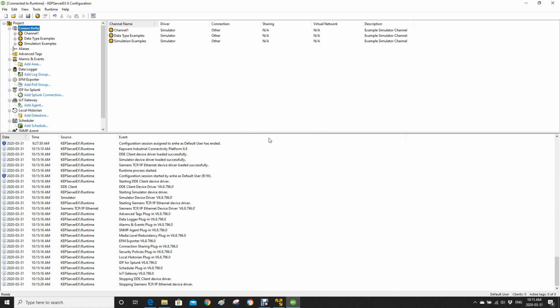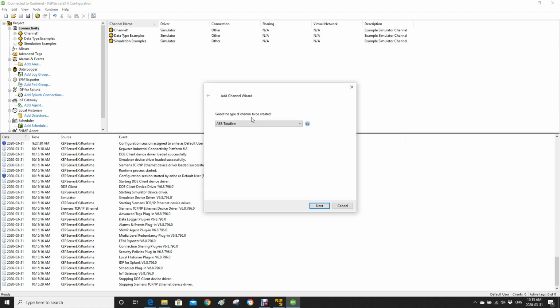If this is the first time, the system will give you some test channel or demonstration channel here. I won't delete this. If you want to do some comparison, you can do that. I will create 2 other new channels here. I will explain why. Firstly, let's set up one connection or channel. That channel is used to communicate with the controller first. So right click, hit new channel, and let's select what kind of thing you need to connect. We need to connect the Siemens controller,